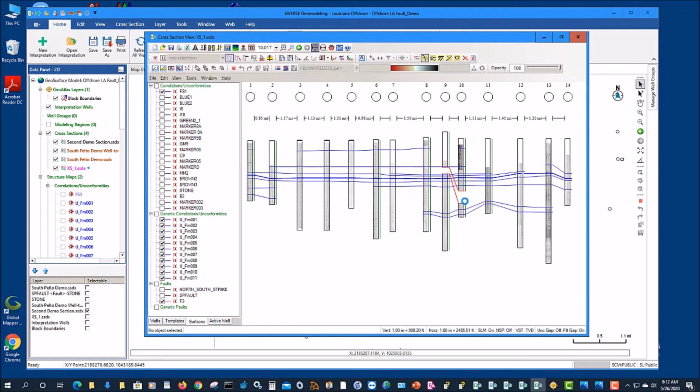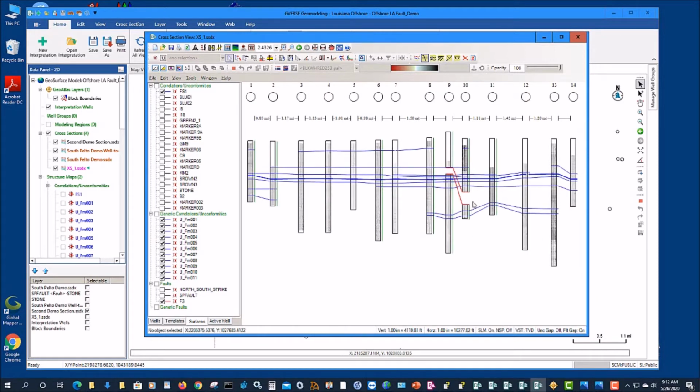So I've got vertical separation calculated, and obviously I've got the fault only picked in a couple of places. Oh, in fact, it actually looks like there might be something going on over here. Let me go back to my fault picker, make sure F3 is highlighted, and I'll go ahead and pick the fault here as well. And it gapped base. It's essentially extrapolated the gap, and that looks reasonable. I'll go back and hit the tab key and adjust the gap slightly. All right.